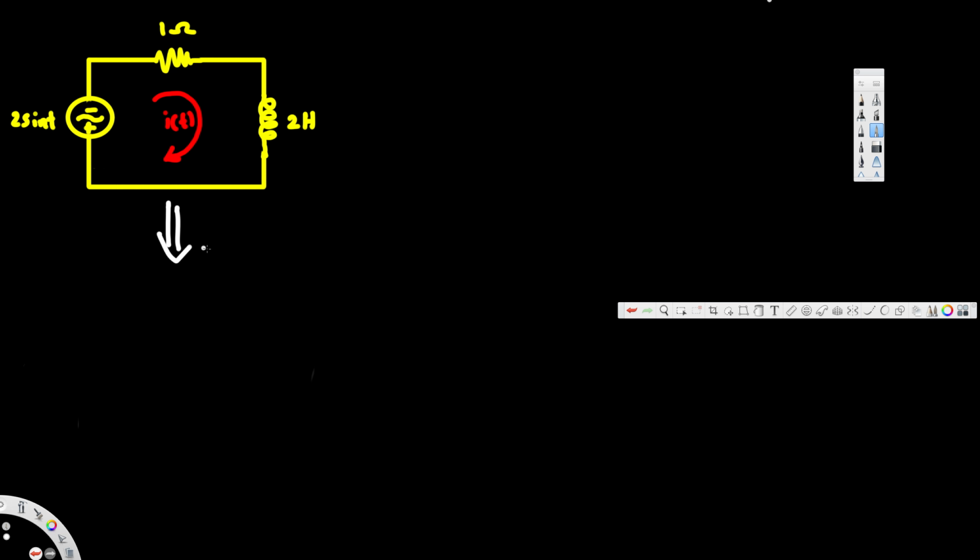Here we are going to have the new circuit. The new circuit is going to look like this, okay? And when we convert this source in the new circuit, we are going to have this amplitude and the angle. That's going to be our voltage source. So this voltage source is going to turn into 2, and this is 0 degree, but since we have sine, we have to put a negative 90. So 0 minus 90 is going to become negative 90 degrees, okay?